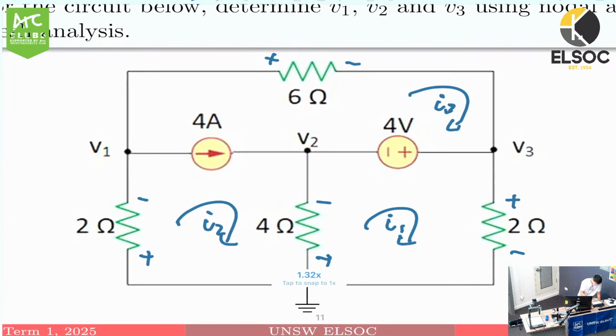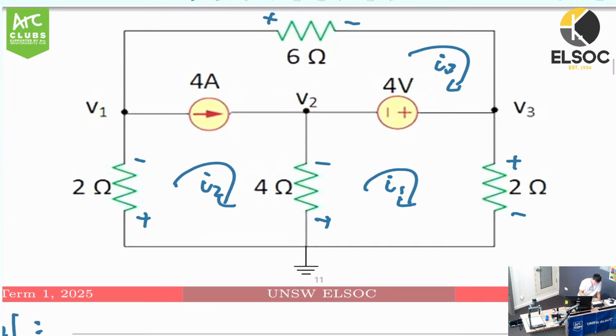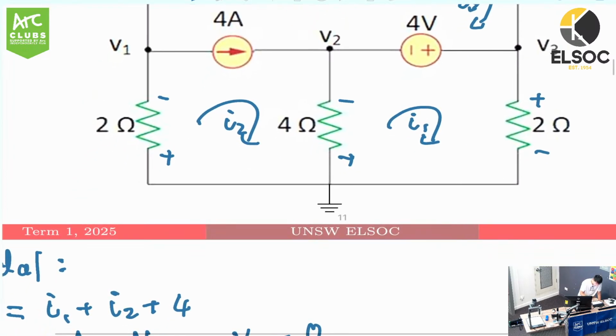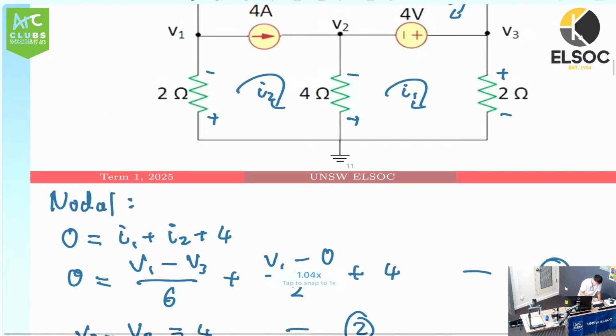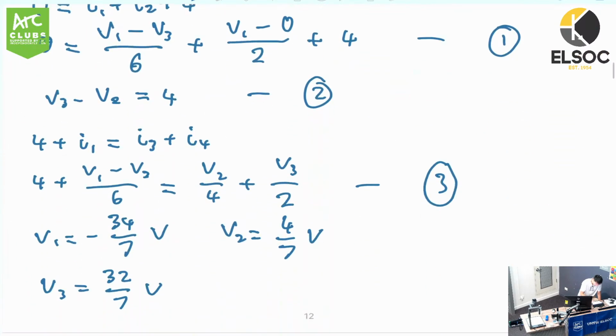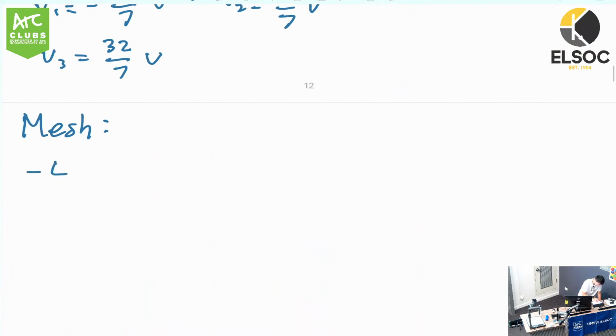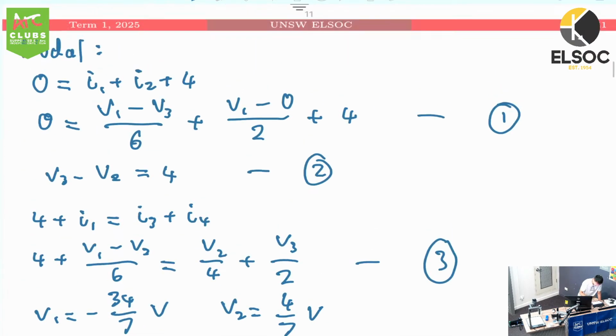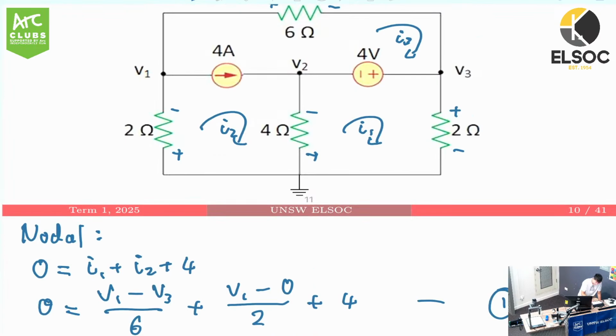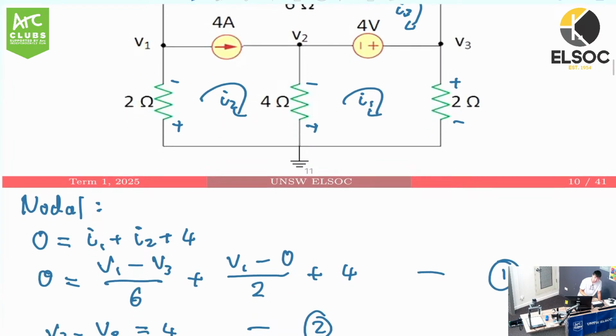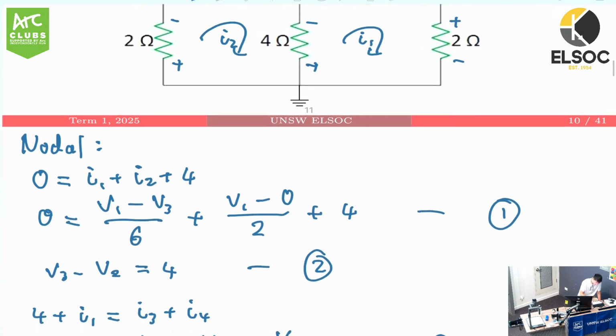Okay. So we can start with I1. We're going to apply KVL and we're going to equate the voltage drops and gains across this mesh. I'm going to set that equal to 0. So let's start at the top over here. We have a 4-volt battery, so we can just say -4. And then we have a 2 ohm resistor here. We want to write the resistor in terms of voltage, so we're going to use Ohm's law, V equals IR.